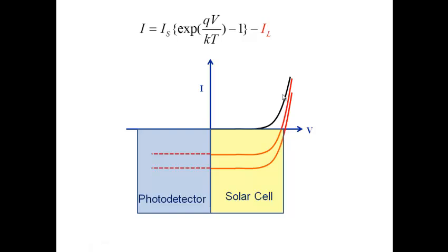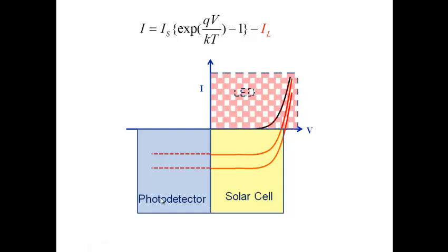In terms of optical properties, let's talk about the PN junction as an optoelectronic device, where optical effects are there, electrical effects are there. Here we said photodetector. Here we say solar cell. What about the first quadrant? The photodiode is here. Photodetector is photodiode. Huh? LED. This is where you have an LED. Why LED? Well, what do you do in forward bias? You inject an electron and you inject a hole. The electron and the hole recombine. The excess energy is given off as a photon. So that's where it's acting as an LED.